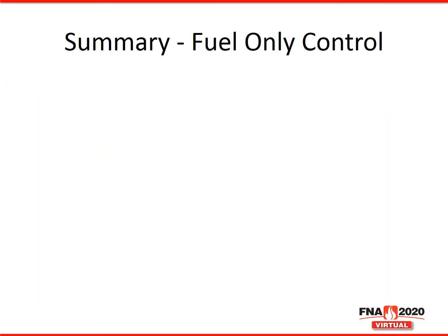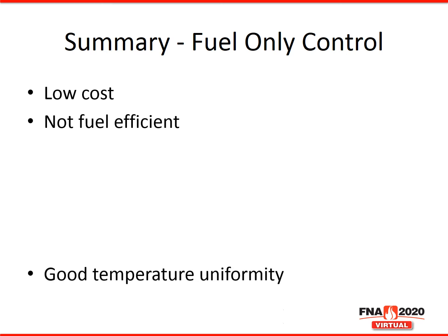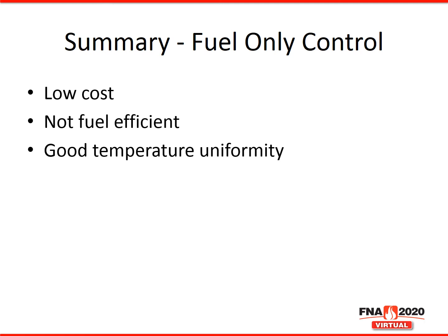Let's summarize fuel-only control. Fuel-only control is low cost due to the controls being simple and few components needed. This control is not efficient because we are dumping all the extra air in the system and it has to be heated up. The upside of the extra air is all that stirring to get good temperature uniformity.